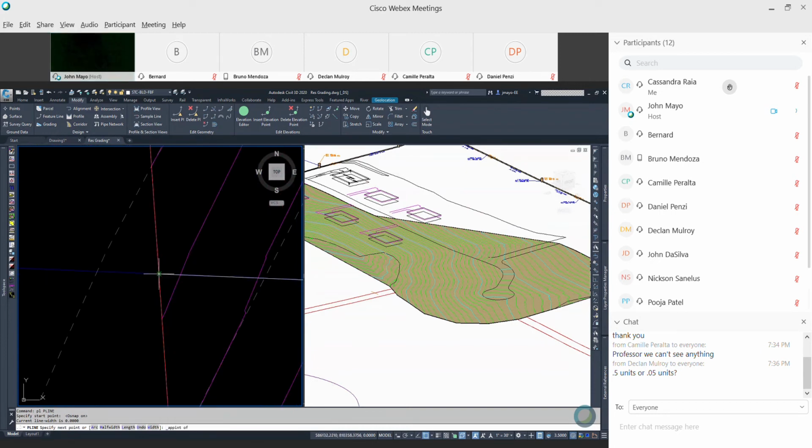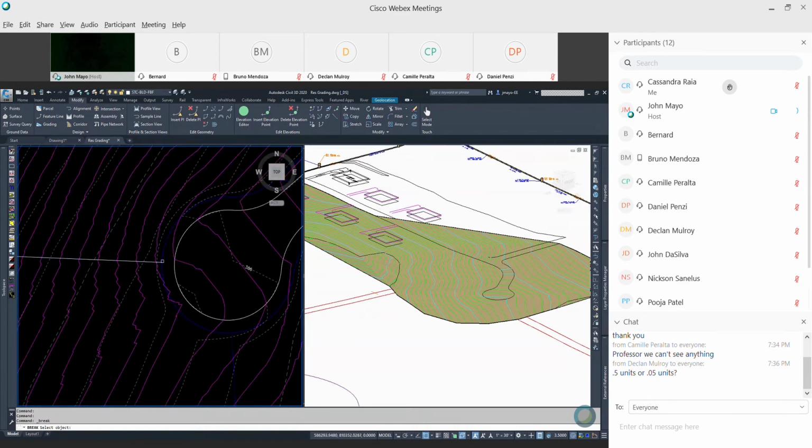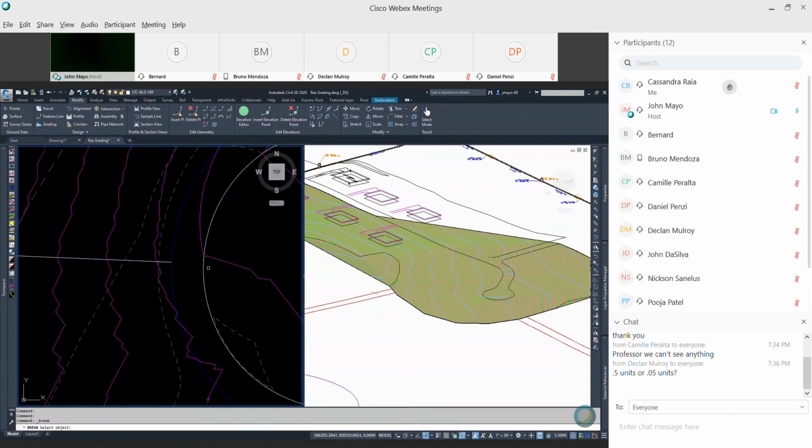And we'll paste them together when we're done, just like you did on your roadway design. I'm going to use the 1 point break, and if I break the limit of disturbance at that polyline I drew, and note I can even do it with that distance there. It's going to interpret it down, and I can connect this, extend.